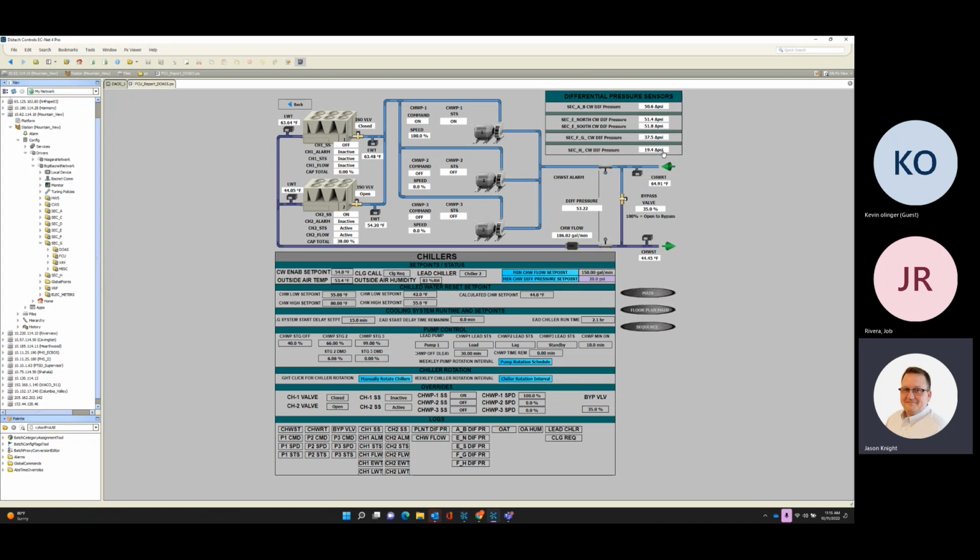And just a little backstory, a job this big and this complicated, as we learn the personality of the building, meaning now we have students in there, we have teachers in there, we actually have live heating and cooling loads that we see fluctuate every 45 minutes to an hour. We see when the kids are leaving the rooms, we see when they're entering the rooms, we see the CO2 levels going up and down, and we're trying to go through this tremendous amount of data and tune loops individually for different classrooms.